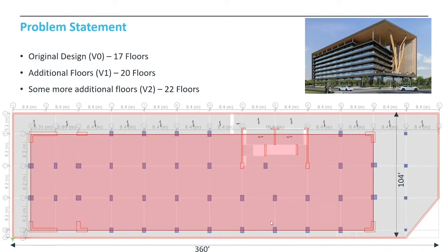Yes, so for the material properties, whatever concrete has come on the site, we instructed them to follow the same quality control that they are following for the other parts of the building, which is the fresh construction. So the number of cubes that they check or number of cores that they take is the same pattern which they use for the new construction.